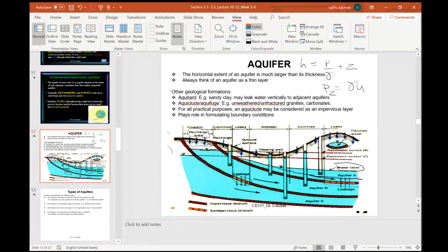Okay, so the various methods of measuring pressure: one, you have the barometer, which is an inverted tube. You can fill it with mercury, which will rise to 760 millimeters, equivalent to the atmospheric pressure. And you have the Bourdon tube gauge, and the piezometer and manometer. The piezometer is simply a tube inserted in a pipeline, in which water rises, and the height of water is the pressure inside the pipeline. That corresponds to the piezometric height, the piezometric head.